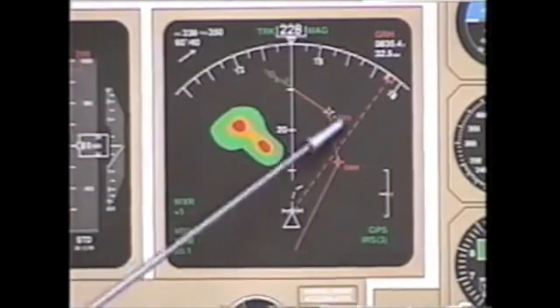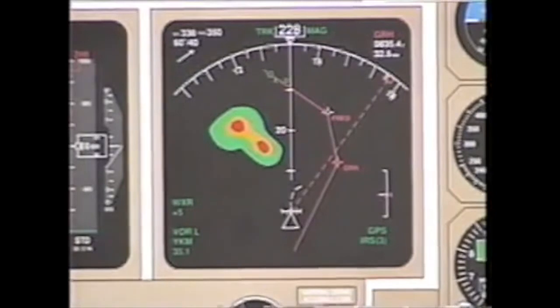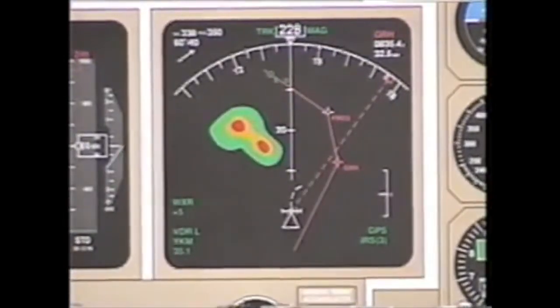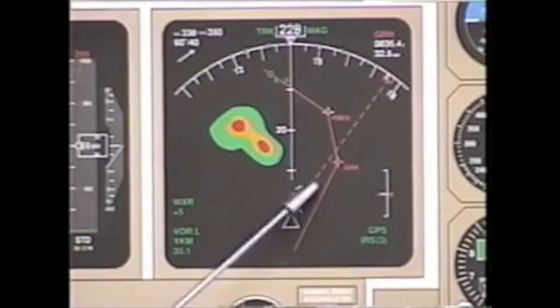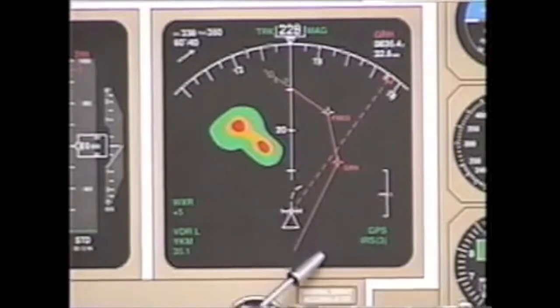The route line on your nav display, it is possible to have 4 different route lines displayed. A solid magenta line is the active route, be it route 1 or route 2. A dashed white line is a modification to this active route. A dashed blue line would appear for the inactive route, and a dashed magenta line, not to be confused with this dashed magenta line that goes out to the heading bug. The other dashed magenta line is an offset.